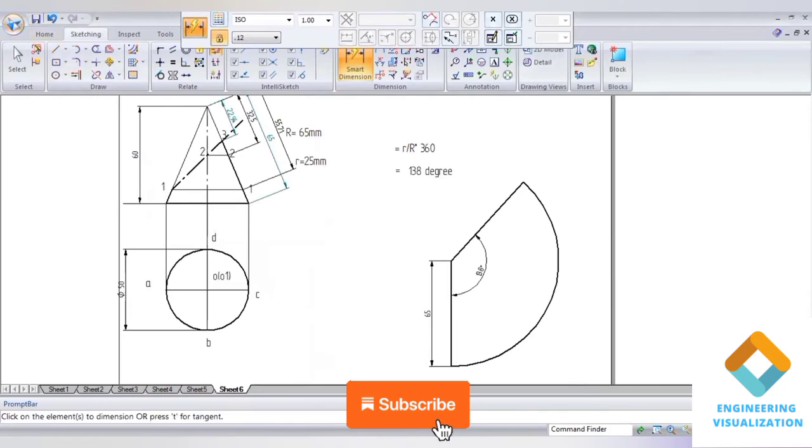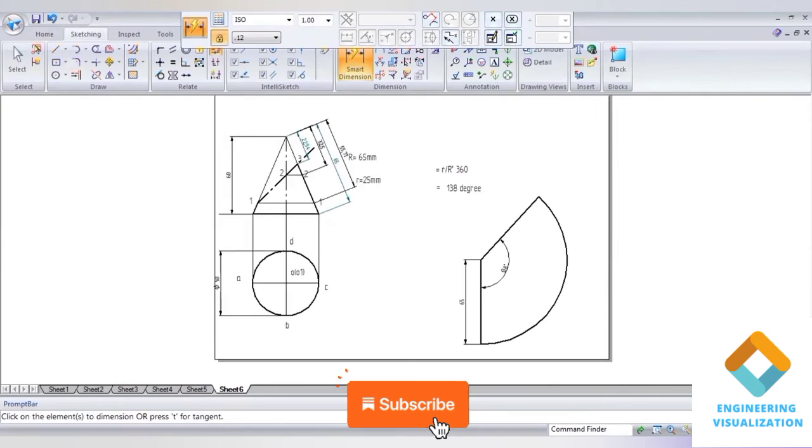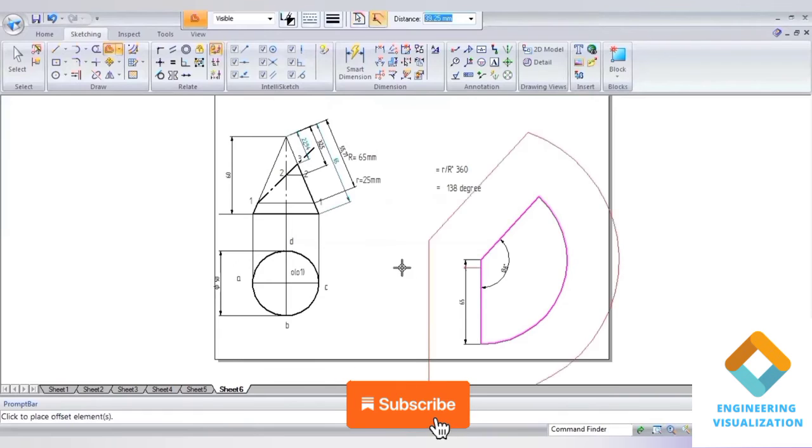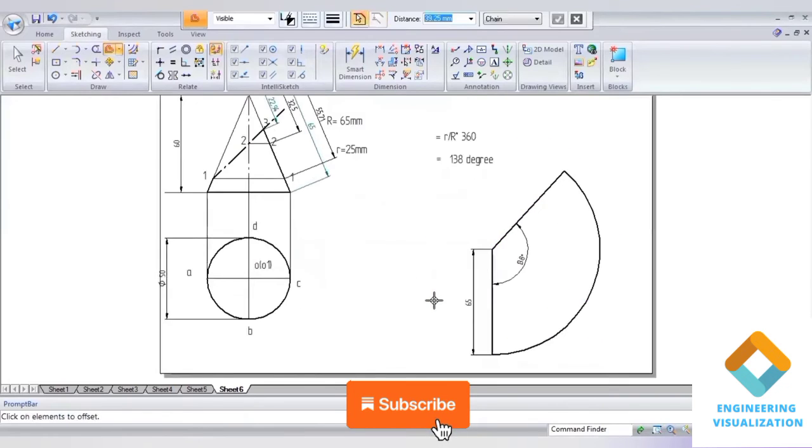So for now, first we have to divide this arc area, that is the cone area, into 4 equal parts. To divide this into 4 equal parts, we have to use the arc by center command. Here in Solid Edge ST4 we cannot divide that area using the angle command. That means we should go to the arc by center command only.